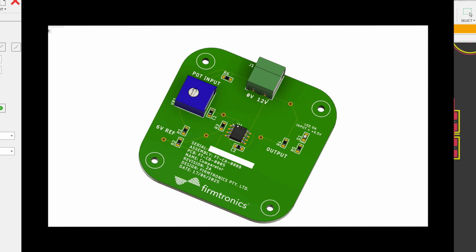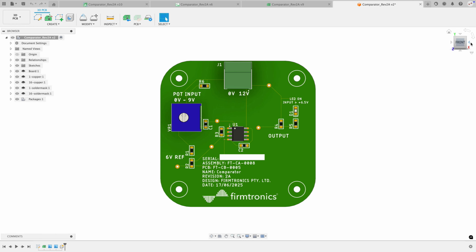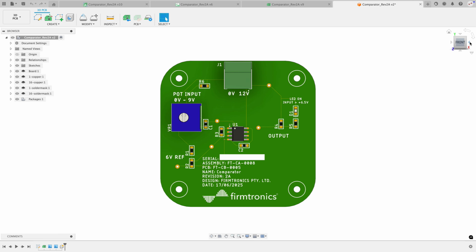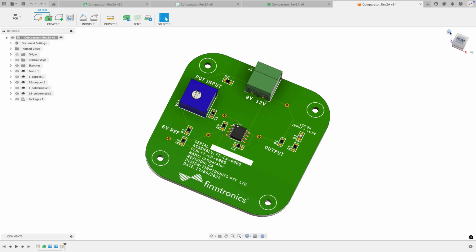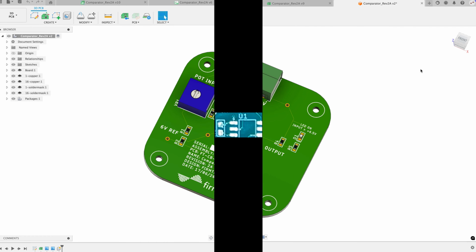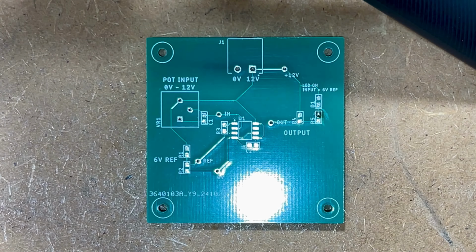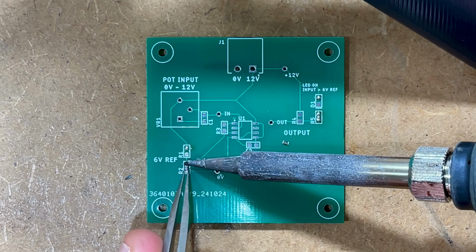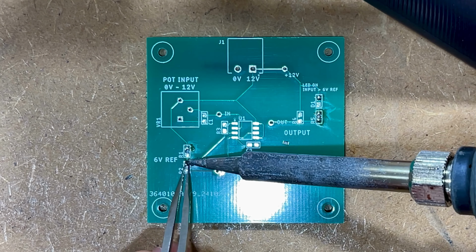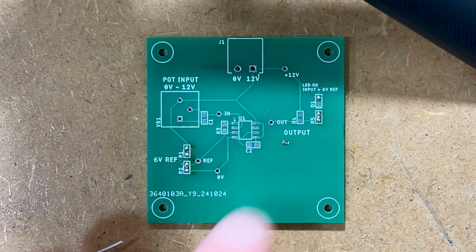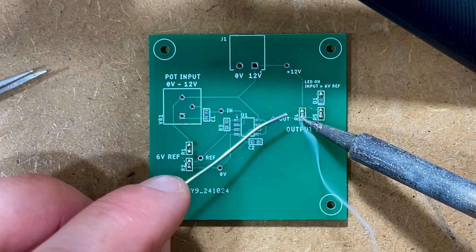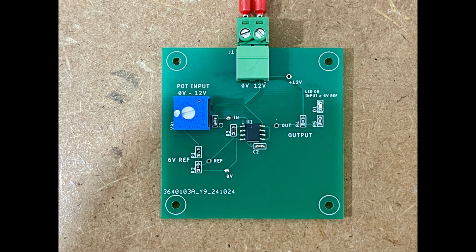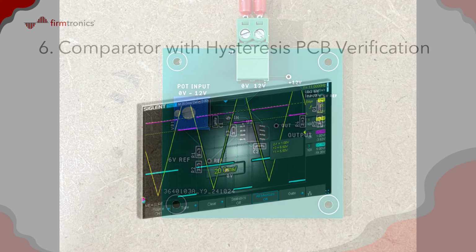The schematics and PCB layout will be designed using Fusion Electronics by Autodesk. I normally send all my PCB designs to JLC PCB, as they are low cost for good quality PCBs, and their website makes ordering the design nice and simple. It normally only takes a week to receive the PCB design. Once received, I first hand solder on all the small 0603 resistors and capacitors, followed by the larger components, and then I power up and test, and hope that I haven't buggered up such a small and simple design.